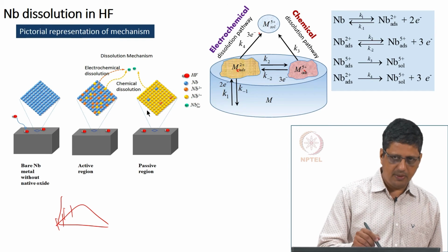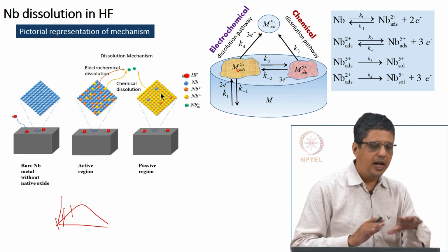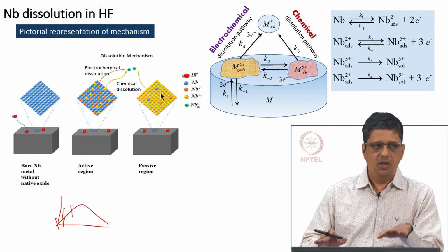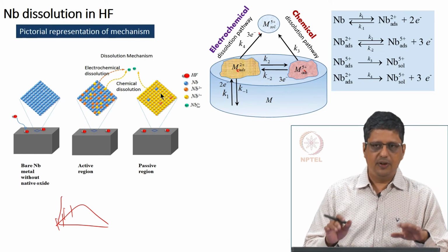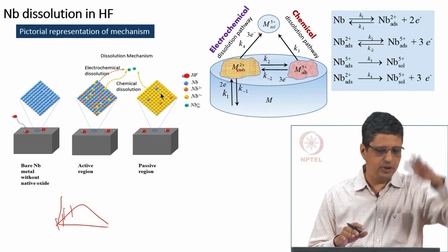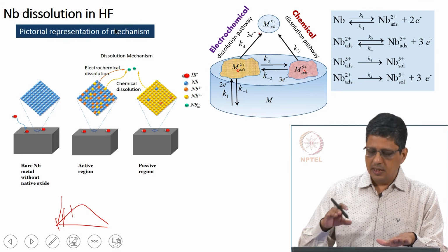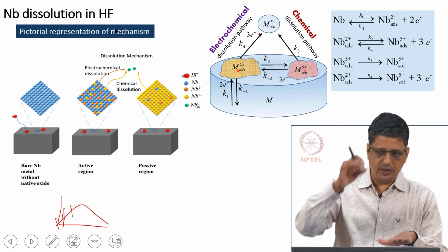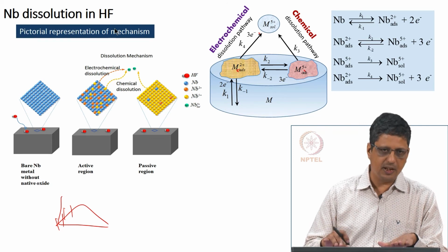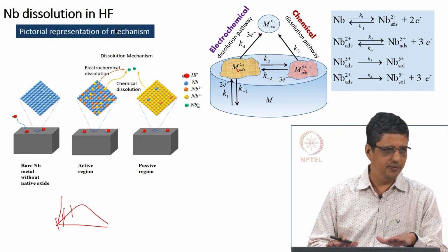There is still some niobium left, there is still some suboxide left under steady state condition. Left meaning I do not mean to say that pentoxide remains there, some suboxide remains and niobium remains. What I mean to say is net, if I look at it now versus if I look at it later, surface coverage, that means some pentoxide might have gone into solution, this might have become niobium now, because underlying metal is exposed. Some of the suboxide might have gone into solution and exposed the underlying material. Some of the suboxide might have converted to pentoxide, that means it is not moved out, but the color has changed, color here is just a representation.